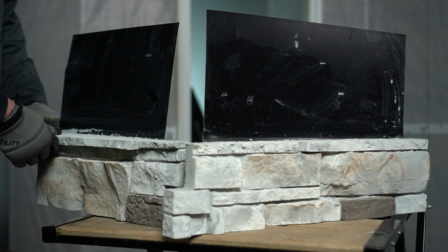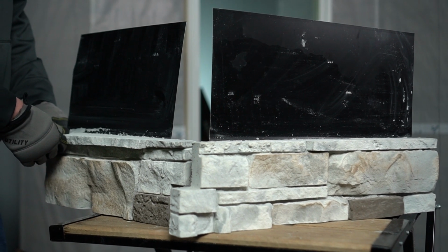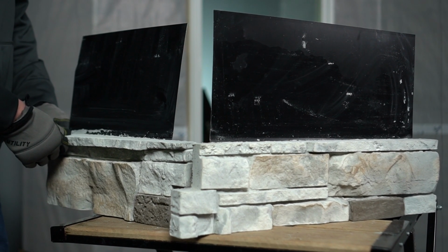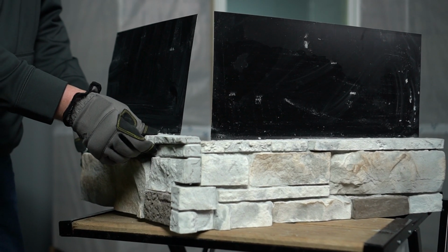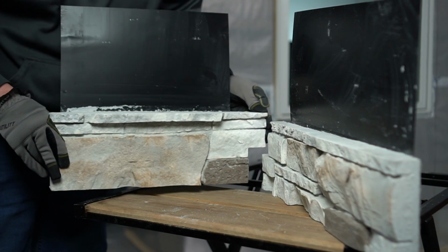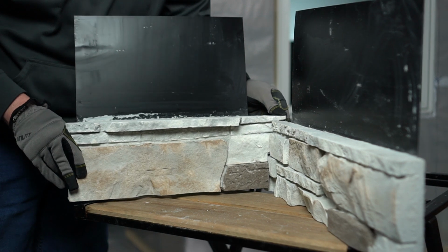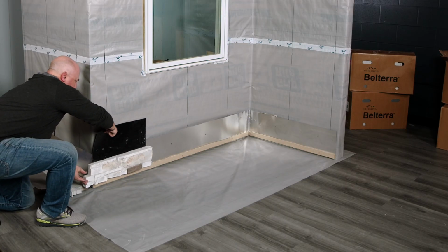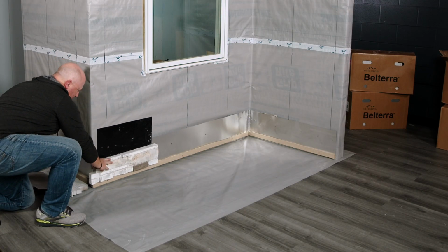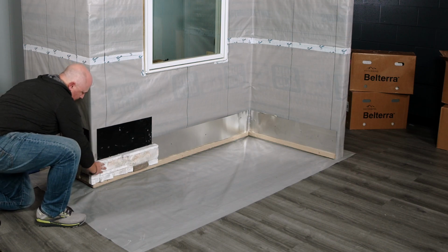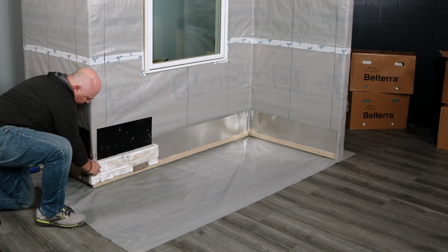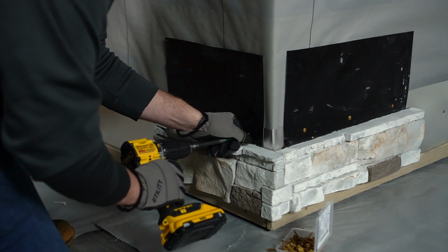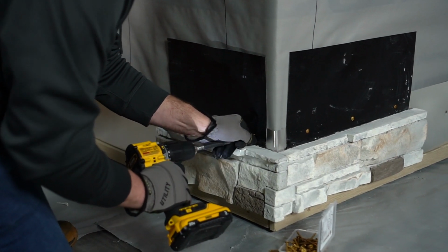Silvermine Stone corners are a 2-piece corner system with one 18-inch panel and one 24-inch panel that are designed to overlap on one end and may be used for both inside and outside corner applications. For an outside corner, begin by fitting the 2 panels together on the wall. Pay attention to the alignment and reveal of the overlapping tongues. Once you are satisfied with the alignment of the panels, screw the panels to the wall.